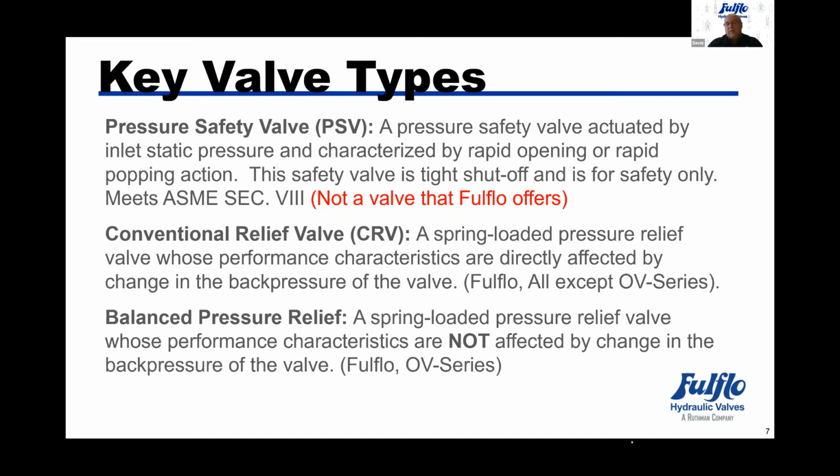This is all the full flow valves except the OV series valve, where the OV series valve is a balanced pressure relief valve. It's spring-loaded pressure relief on the inlet of the valve, but the back pressure does not affect the set pressure at which the valve is going to operate. That's the OV series valve, which we'll talk about as well.